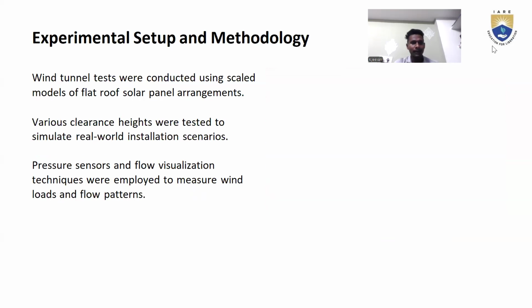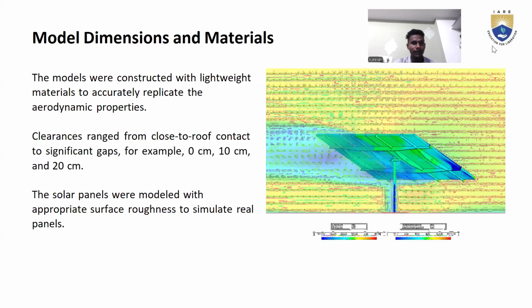Experimental setup and methodology. Wind tunnel tests were conducted using scaled models of flat roof panel arrangements. Various clearance heights were tested to simulate real-world installation. The pressure sensors and flow visualization techniques were employed to measure wind loads and flow patterns.